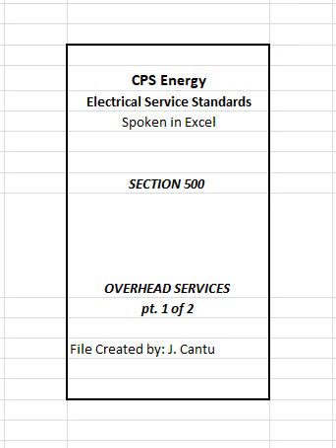4. Where a building is not tall enough to provide anchorage to meet the required clearances, the service raceway may be extended vertically from the metering or service equipment and serve the dual purpose of enclosing the service entrance conductors and supporting the service drop conductors. CPS Energy will furnish and install a raceway clamp with eye-bolt to support the service drop conductors. Service raceways so installed shall meet the requirements for service masts outlined in Article 507 and shown in Figures 503 through 505.